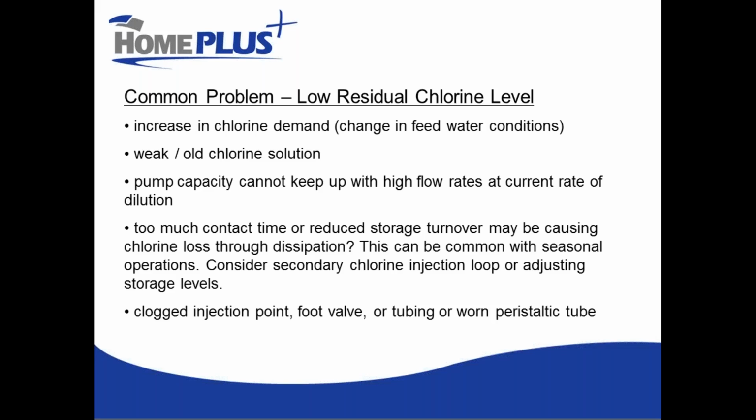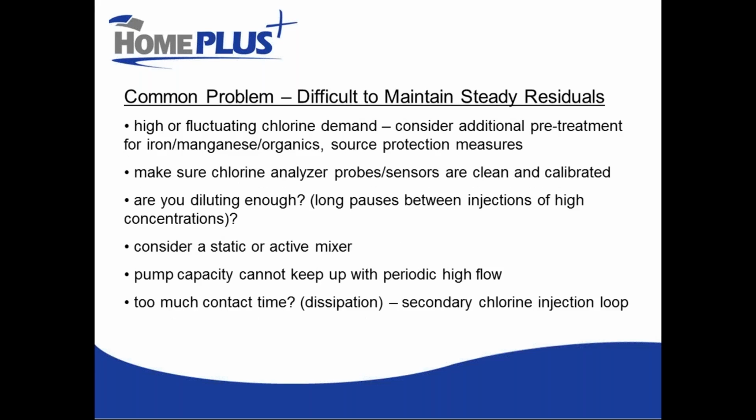You may also have an injection point, foot valve, or tubing that is getting clogged up and restricting the amount of chlorine that the pump is able to inject into the line. So it's something you can certainly pay attention to as well. You may also have a problem where chlorine's not always low, but it's fluctuating. You're having a really hard time dialing into a steady level.